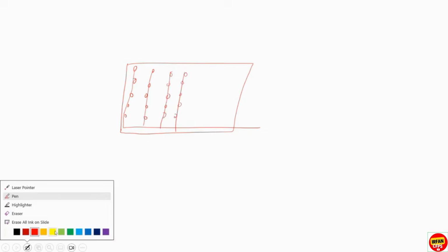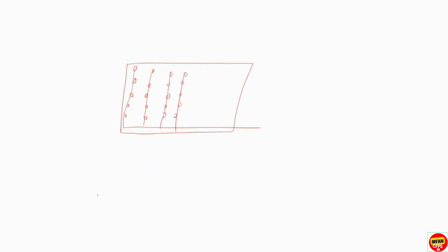So this is the thing. Room piping. So 5 sprinklers, right? 2, 3, 4, 5. Again, you have 1, 2, 3, 4, 5. Same example. Now, as I told you, the length of the design area will be for the remotest floor, remotest area.